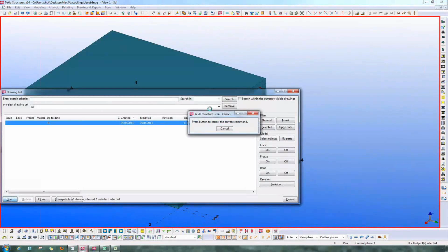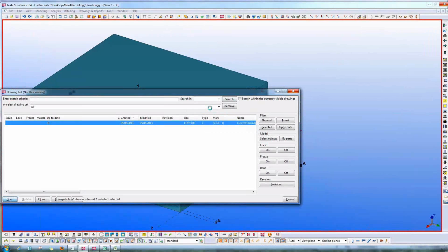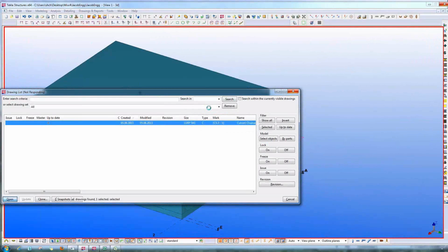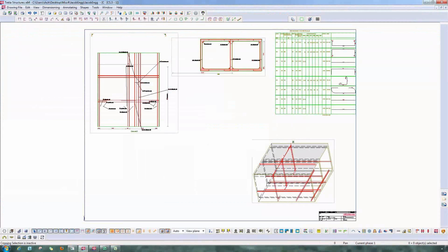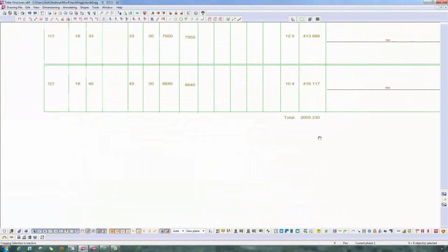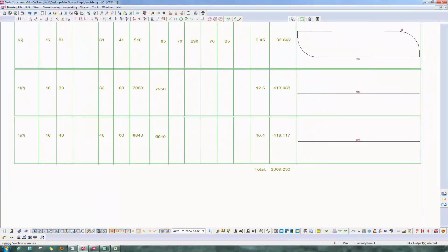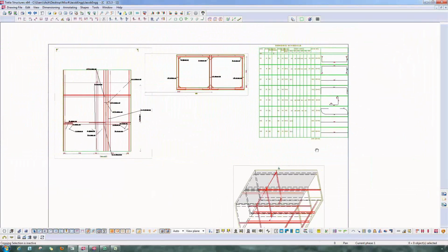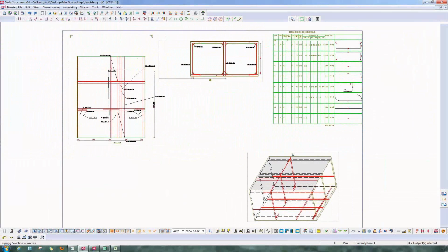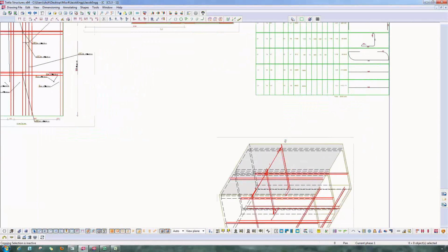So if I open my drawing, so we need to do the numbering in between. Basically, compared with the 2D workflow and the BIM workflow, it updates instantly in all the deliverables. Now we can see the 2009 kgs of the reinforcement is required, so it already updated in the drawing, and even with the new concrete information, it's already taken care of on the drawing side.